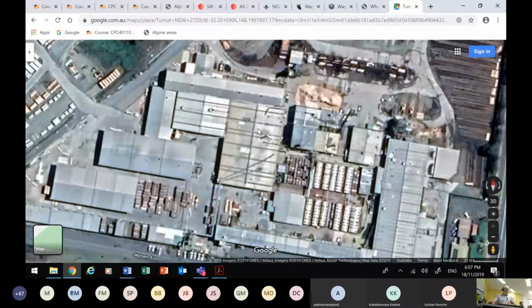A group of us were looking through there one time, and we said, why did you go for timber here? Wouldn't you think that would burn? And they said, well, actually it doesn't. It's got much higher structural adequacy than this building, because if a fire was to occur, the steel would get hot and lose its strength, whereas in this building, the timber would build up a layer of char on the outside of those massive big columns. Once you get charcoal on something, it won't burn anymore unless you've got a lot of small timber around it.